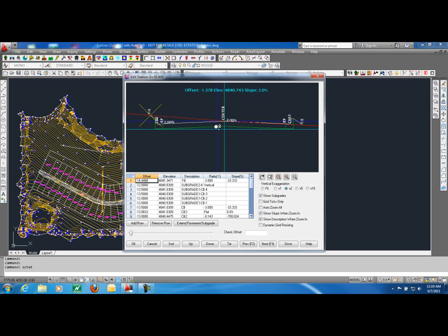So I can simply go in and type new values here. So that's always one option I have. When we look at the sort option, when you're working with design sections, be a little cautious with this option because it will sort these according to offset, and you'll notice that these are not necessarily in numeric order. So my 13.5s would move above this 12, and it will reshape your section. So be a little careful with this on design sections.